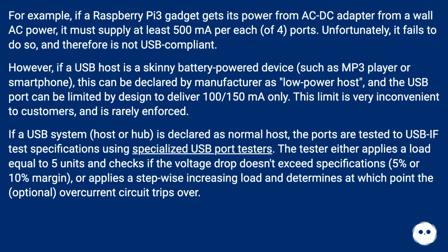However, if a USB host is a skinny battery-powered device, such as an MP3 player or smartphone, this can be declared by the manufacturer as a low-power host, and the USB port can be limited by design to deliver 100/150 mA only. This limit is very inconvenient to customers, and is rarely enforced. If a USB system, host or hub, is declared as a normal host, the ports are tested to USB-IF test specifications using specialized USB port testers.